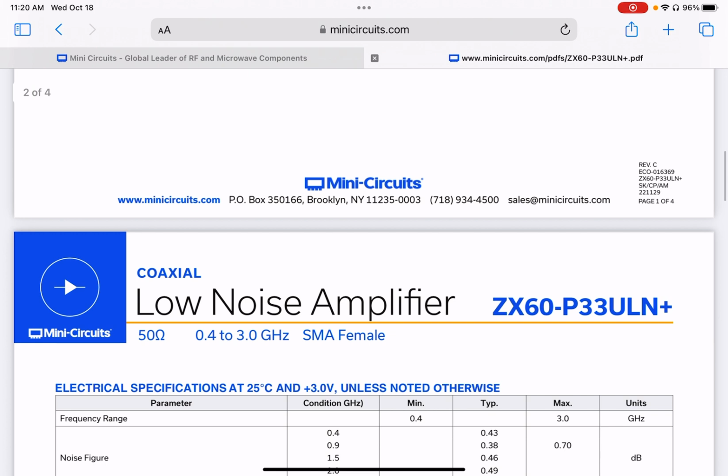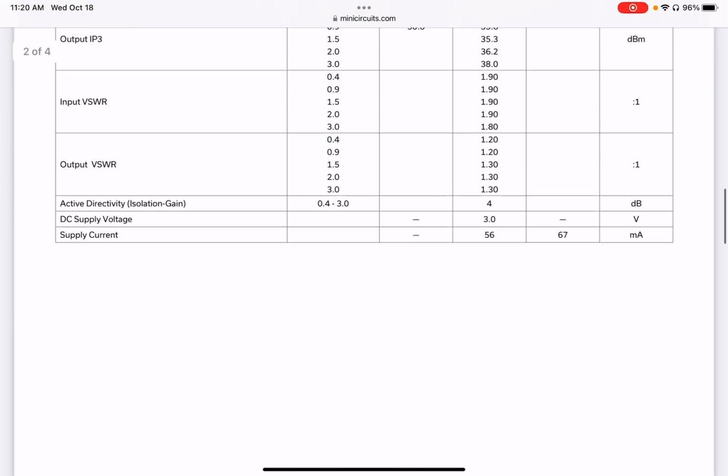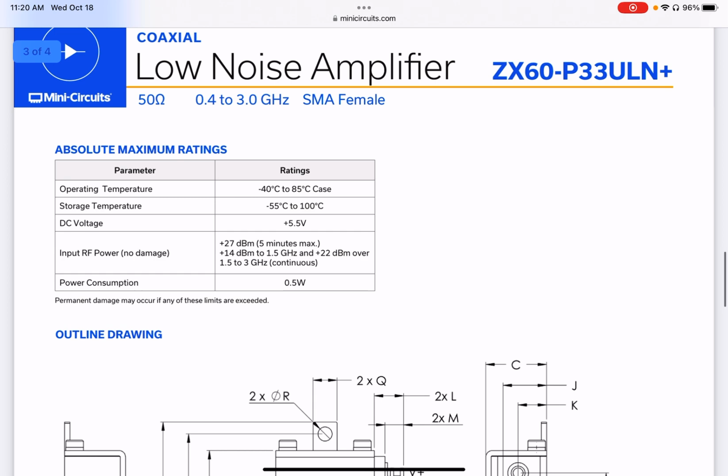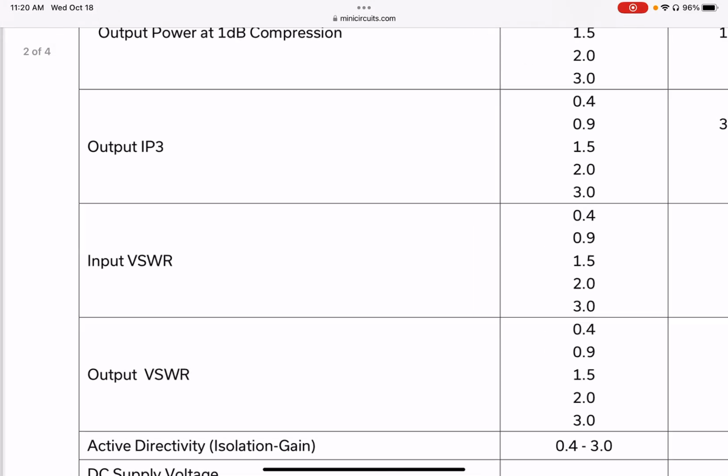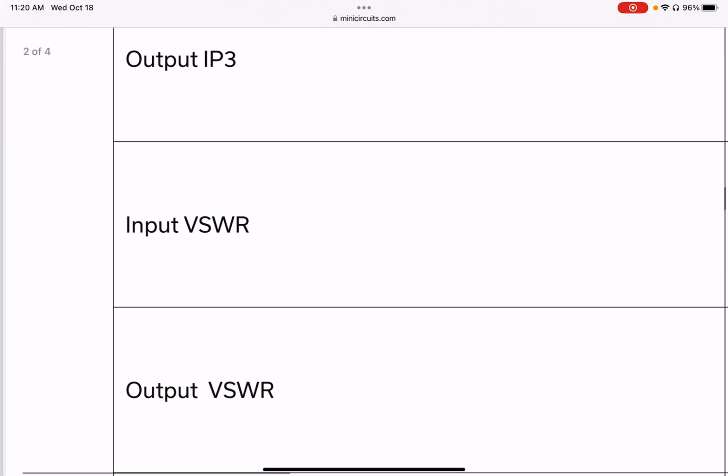So this 50 ohm termination, with manufacturing tolerances and across frequencies, etc., may not always look like a 50 ohm termination. It might change in frequency, because of the input termination being what it is. So here in the specification table, notice they have two parameters. I'll focus on the input voltage standing wave ratio, VSWR.